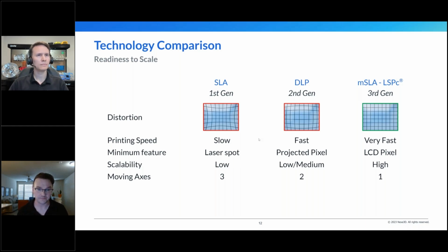Moving into DLP, you end up with kind of the inverse of this. And essentially, when you're using a projection system, think about it like a flashlight. If you're shining a flashlight directly down, you see this beautiful, perfect circle, but then a little bit of diffusion near the edges, right? The light isn't as powerful. Now, if you were to utilize that full space, the parts that you're building in the center are going to come out beautiful, crisp, clean, perfect. And if you look at the edges, they might not be as good, whether that be from a mechanical perspective or fully forming, things like that.